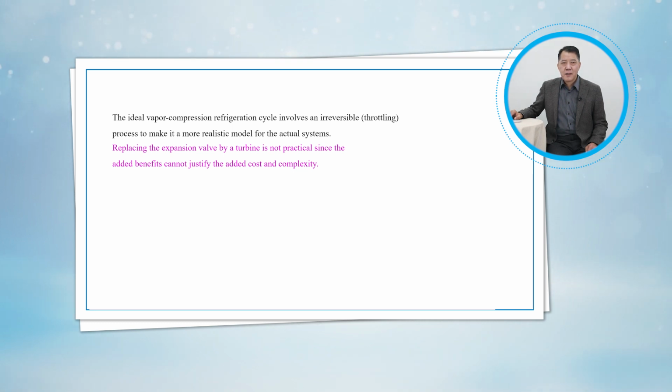As a result, the refrigeration capacity would increase, and the net work input would decrease. Replacing the expansion valve with a turbine is not practical, however, since the added benefits cannot justify the added cost